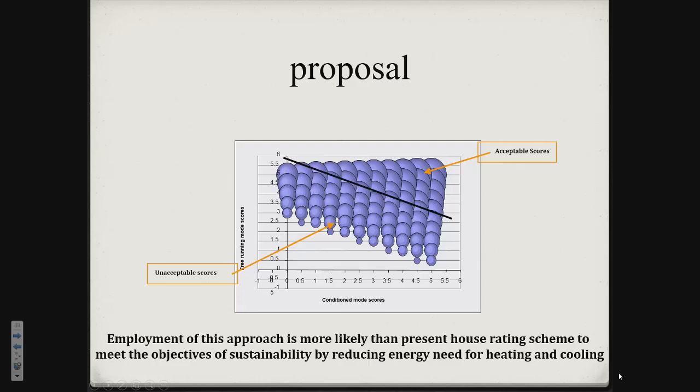If the climate is suitable to promote passive architectural design, it gets 3 star. But if we have a critical climate, where we cannot have indoor comfort conditions during the summer in particular, we had better give more value to the conditioned one. That means 5 star from conditioned and 3 star from free running, the building might get 6 star.